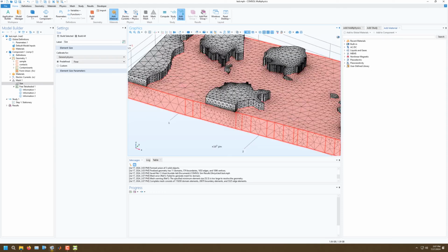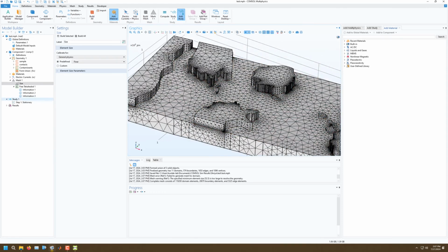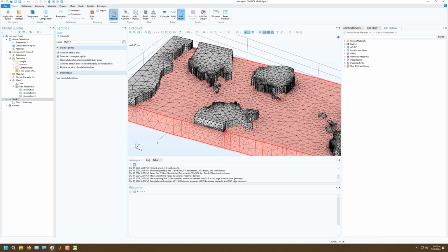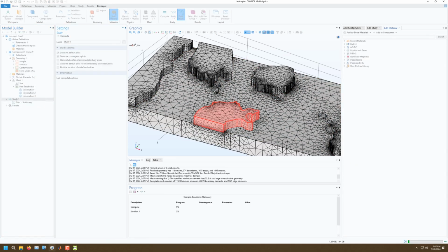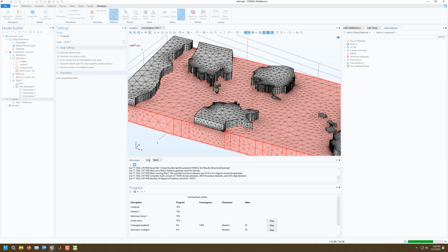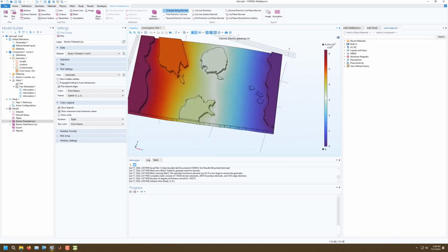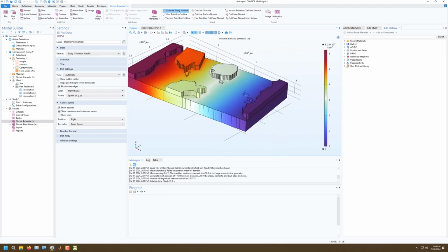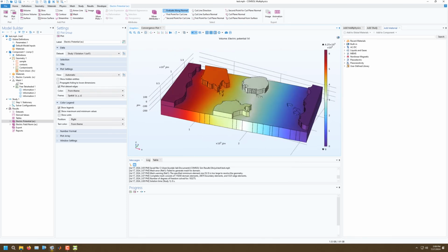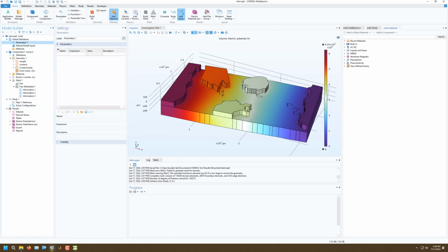Okay, so now it's a bunch of triangles. And what we can now do is hit study. So we're going to study how it looks if this has a conductivity of 1. Looks as you would expect it. So now we're going to study the material, and this is how we will find out what the geometric factor is. So in parameters at the top, we're going to define the resistivity parameter, pxx, and we'll just give it some value.